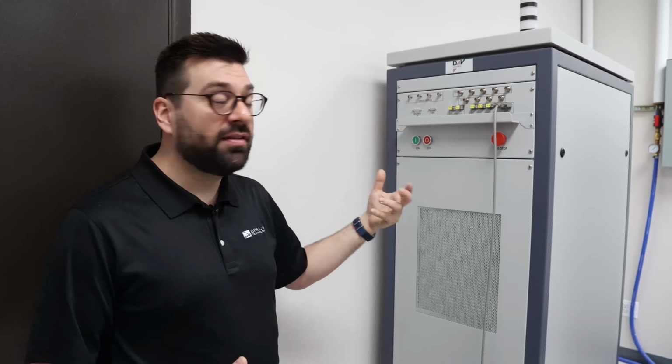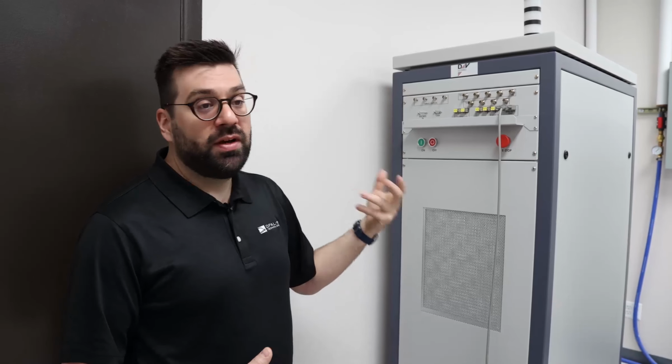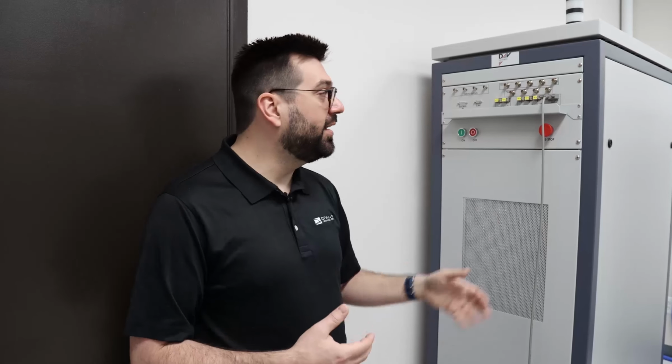It's a DC source, but it's also a DC supply with up to 20 kilohertz bandwidth. So it can not just generate a DC source, but it can actually generate signals up to 20 kilohertz, so you can use that to add noise. OPAL-RT also brings the fast connection with the real-time systems to this equipment. So if in your test sequence you want to do any perturbation on your DC, OPAL-RT with the NI platform can do that modeling and add noise and faults to the DC with such equipment. So this is the full overview of the application that we have as hardware.